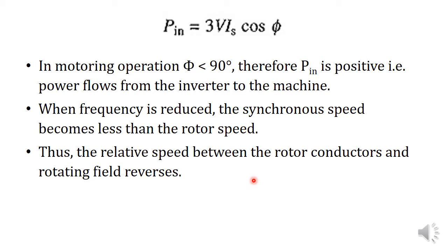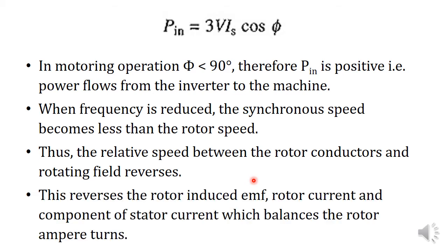Since the relative speed becomes negative, the EMF induced in the rotor, which opposes the relative speed, or tries to nullify it, reverses.